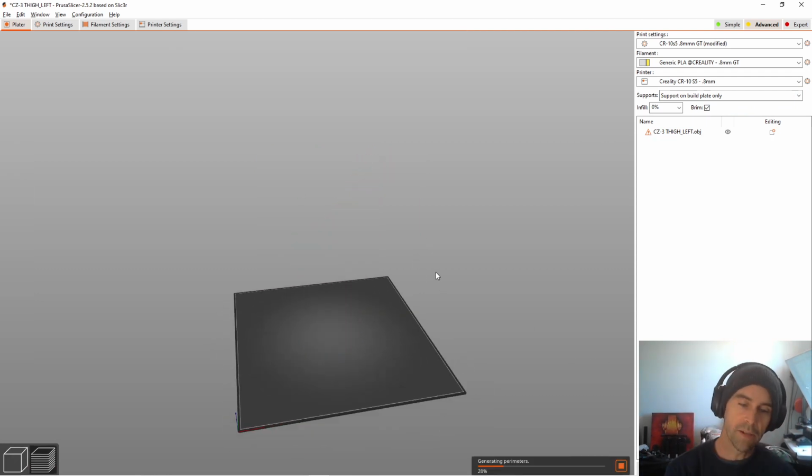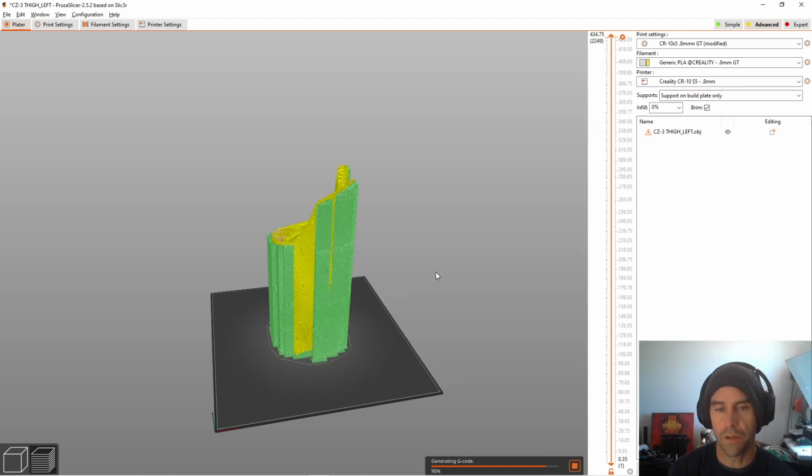We're going to see the time difference here. It's probably going to be close to the time it takes with the lightning infill. But this has no infill. Remember, I turned the infill off. So this is just support material on the outside for the full piece. It's a lot more material. Look at that. Just look how it goes all the way up to support this little thing.